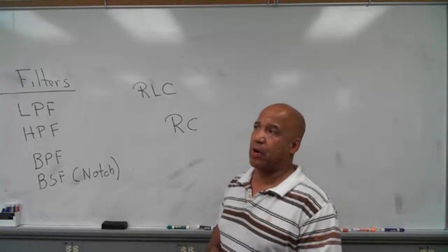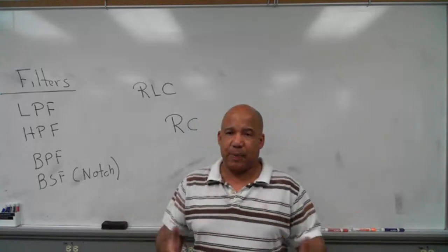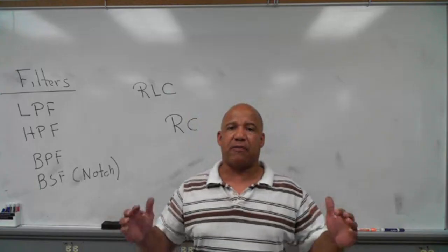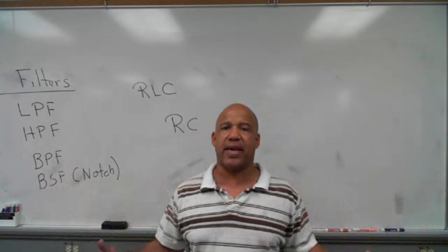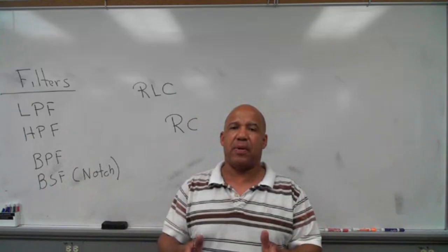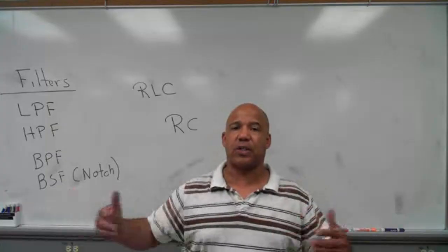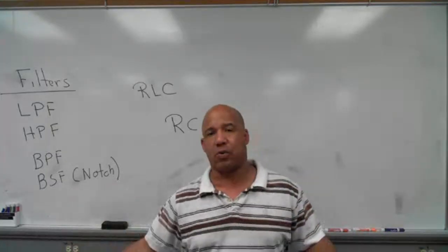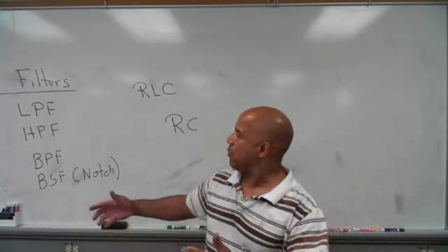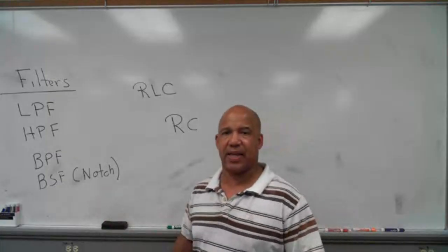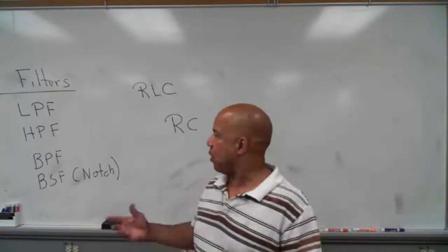It was an audio application where we have a problem that we have this thing called a speaker, and the speaker has a certain bandwidth, and the bandwidth of the signals is way wider than one single speaker can handle. So we said, all right, maybe we can divide this bandwidth up into chunks, the bandwidth being human audio bandwidth. And instead of using one speaker, we'll use three speakers that have different bandwidths, one for the lows, one for the mids, one for the highs. And we just kind of thought through it to see, well, how would we connect things up? What kind of filters would I need to get an audio system to work and have what you might call high fidelity? So we worked through that.